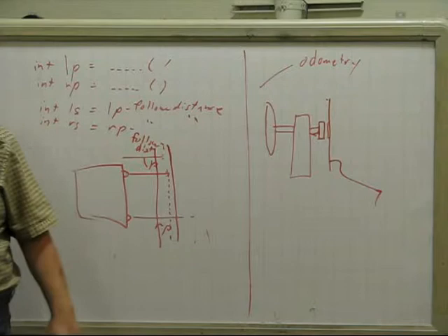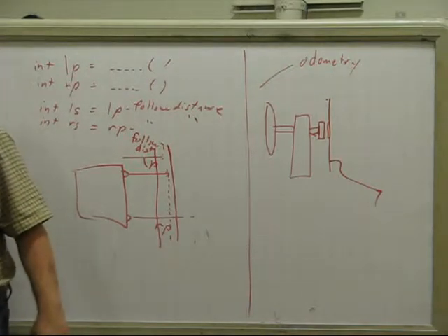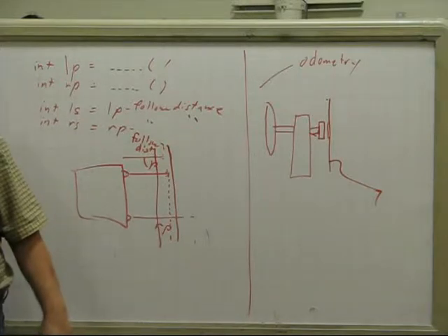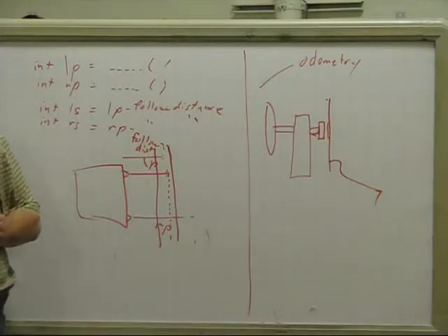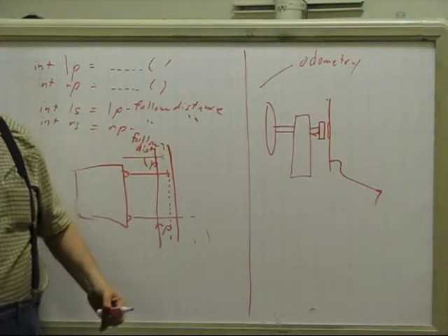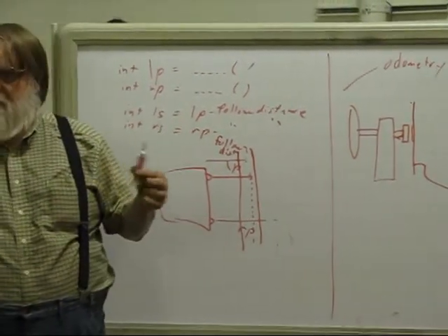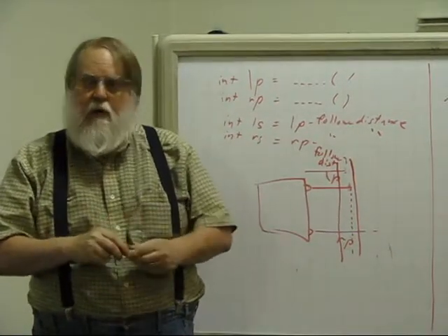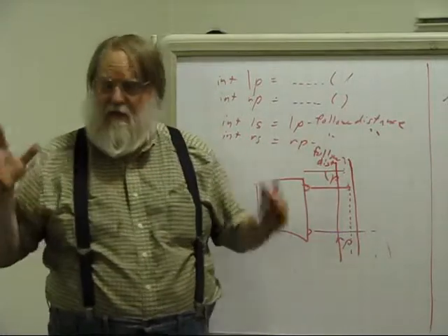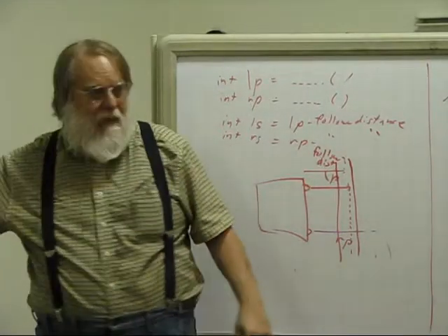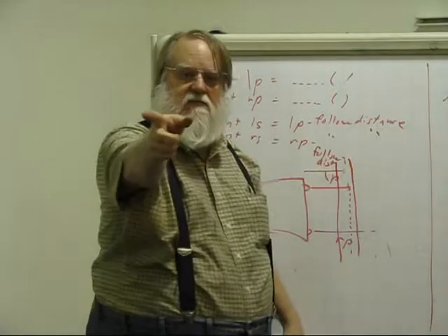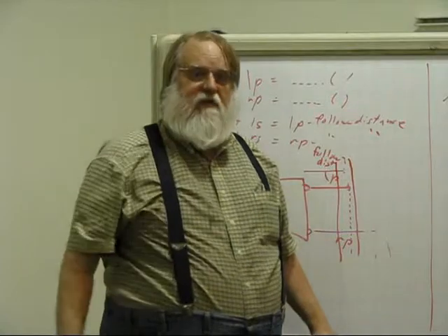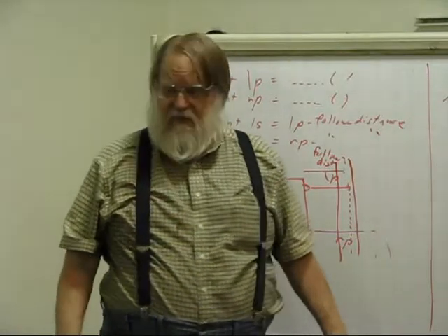When we do odometry, now we can make our robot go in a straight line. In addition, we can do all the code that allows us to say, I'm in position here, and I want to go over there. And it will accurately go there. You'll get just small amounts of slippage in your wheels. Eventually it'll get lost, but there's things you can do. So we could probably make a robot that comes down here, turns right, goes down there, turns left, and goes out the door. We could probably get that to happen about 50% of the time if we do odometry.